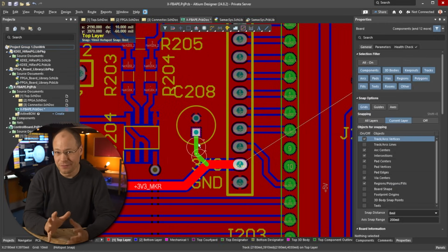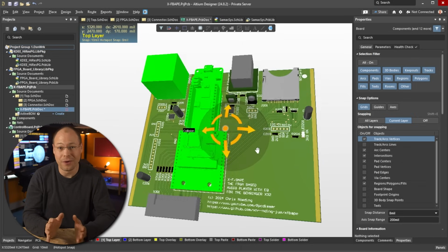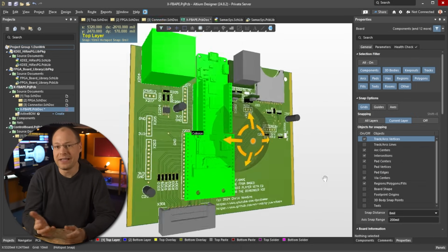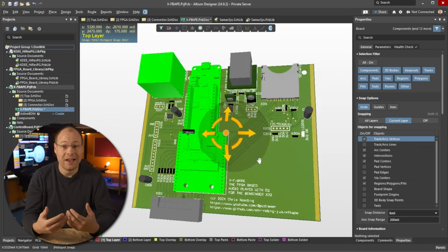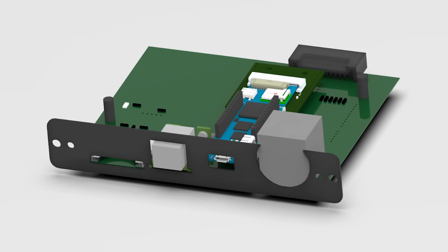I took a bit of risk with this project. I actually had the board manufactured without even looking at all the protocols. Since we can freely assign all lines in the FPGA, I'm fully relying on this flexibility at this point, in case my offline reverse engineering of the board is not correct. My final goal would be to use the X-Live controls in the X32 to select individual MP3 files on the SD card, but the minimum goal is to receive and return audio data from and to the X32 in the first place.